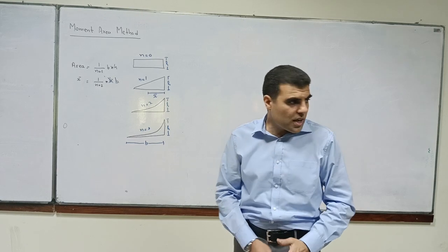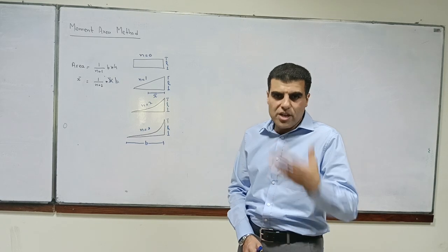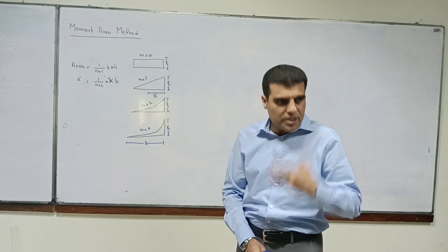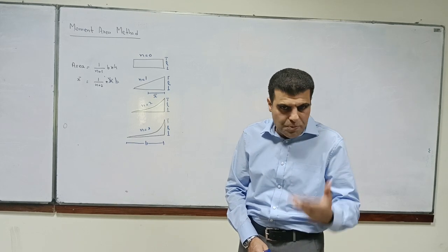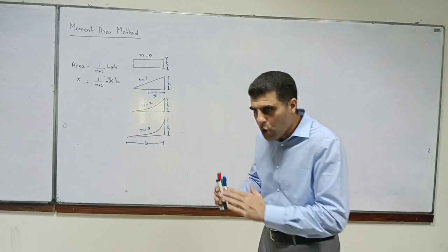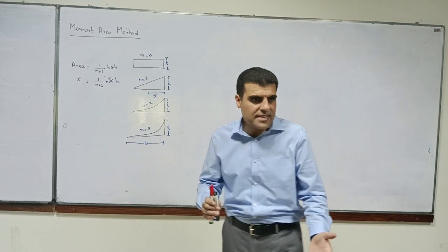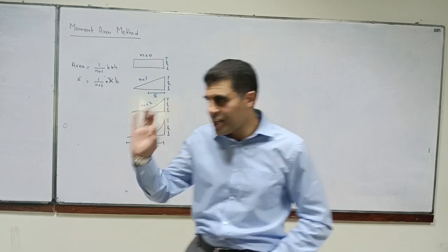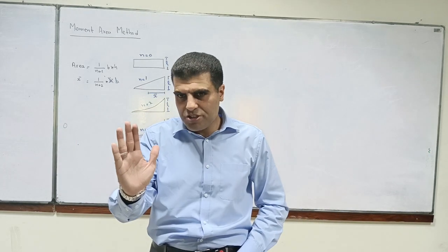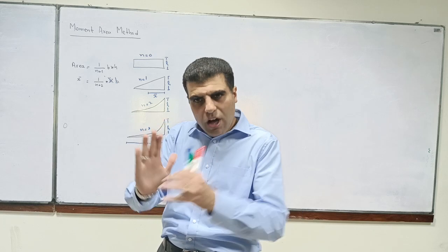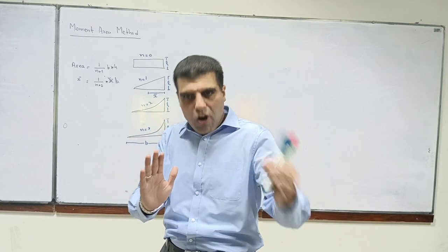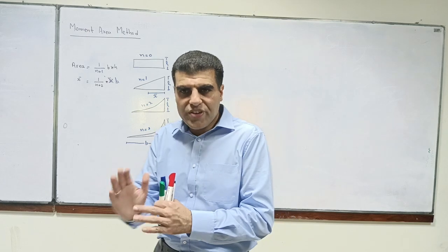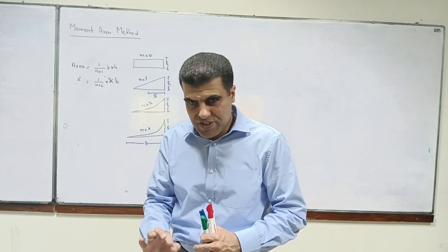Therefore we feel the need for bending moment diagrams by parts, which means that for each and every load we draw a separate bending moment diagram. You take one strategic point inside your structure and draw the bending moment diagrams for all the applied loads, considering that strategic point as fixed.